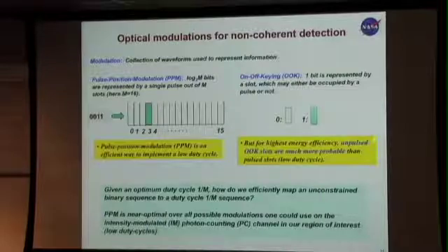So when you have a low duty cycle, then pulse position modulation is a more regular form of this. It says instead of flipping a coin with a very small probability and producing a 1, how about putting exactly 1 out of every m slots? It's more or less the same thing as picking a 1 with probability 1 out of m. So this is an illustration for m equals 16, occupying slots 0 through 15. The modulation rule says put 1 pulse in there and only 1.